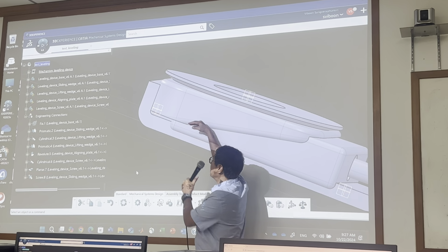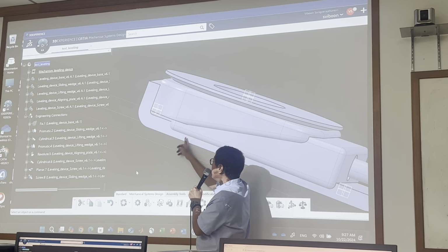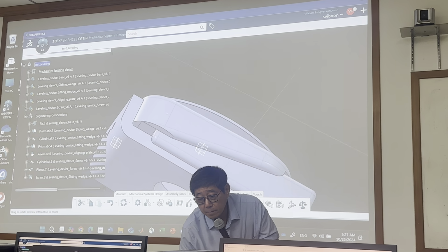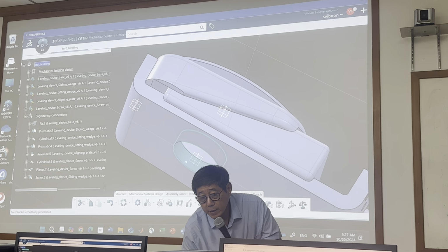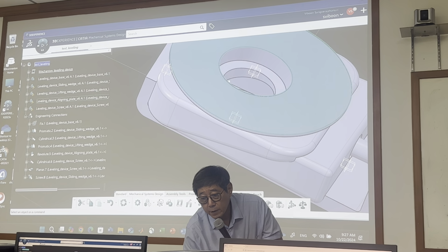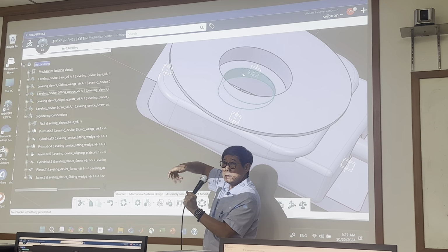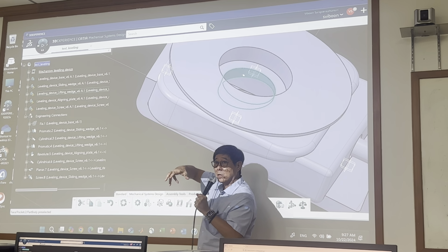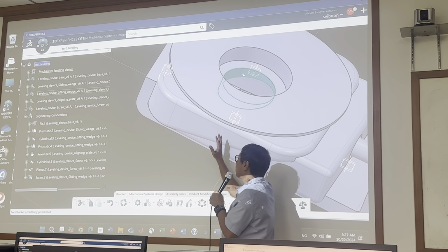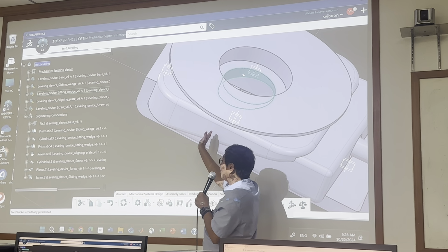See? You want just this one, just move this direction. But if you set just coincident between this and the hole, it means that this one can rotate as well. Move this one and can rotate because it's cylindrical. In that case, you need to make this one not rotate.